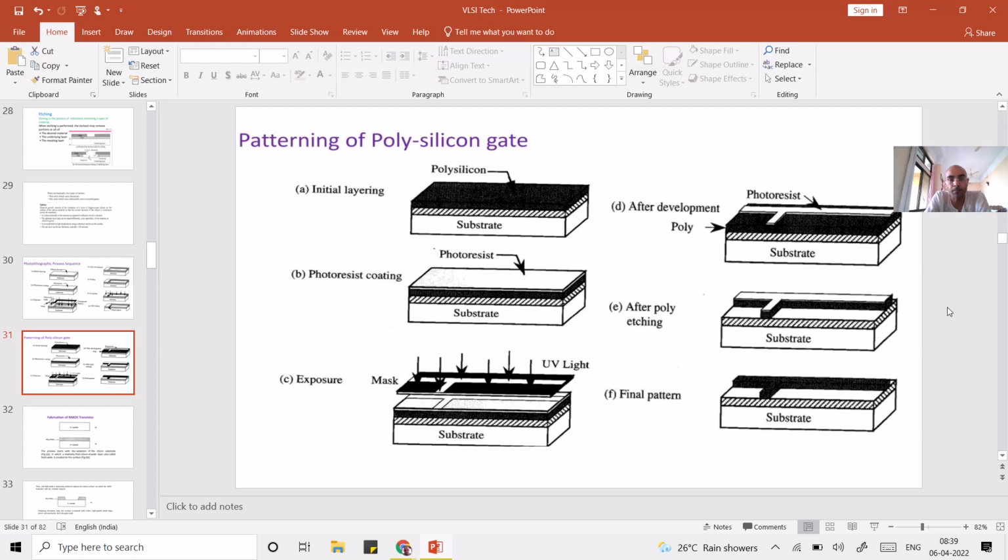One of the problems is electromigration, which we have already studied during the first unit. But there was no better solution than aluminum, so aluminum was the best solution. People used aluminum to form the gate contact, as well as the contacts with the other terminals, the source region and drain region, and also to form the interconnects between the various devices.